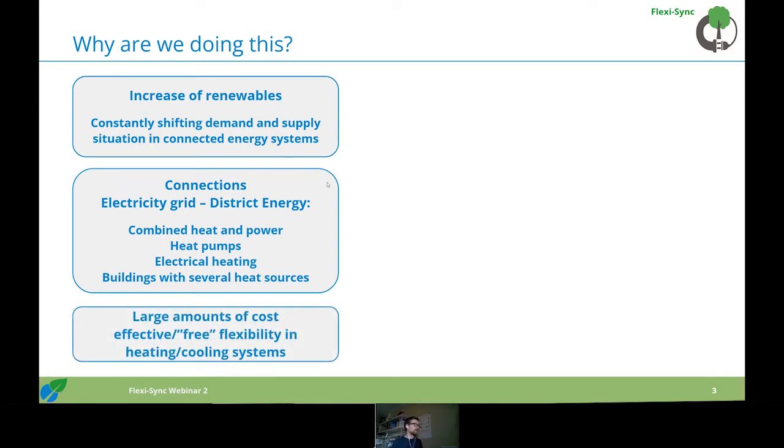And these heat pumps are normally run prioritizing the heat pump all the time and then peaking with district heat. But if we look at the last picture, we should really turn them off when the electricity prices are high and operate them more flexibly. And these are just some examples of flexibility, but there are also a lot of other types of flexibility in district heating grids. You have the grid itself, you have hot water storage tanks, for example, and demand flexibility.